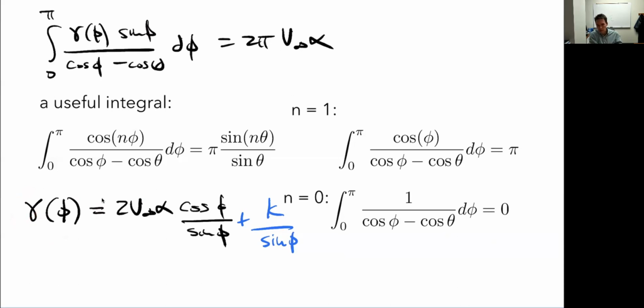That's a problem because I can get any circulation that I want now. So which one is the right solution? In some sense, actually, we shouldn't be too surprised that this happened, because recall that what we're doing is we're solving this irrotational flow field where if I took control volumes anywhere, the circulation is zero everywhere. By definition, right, it's irrotational.